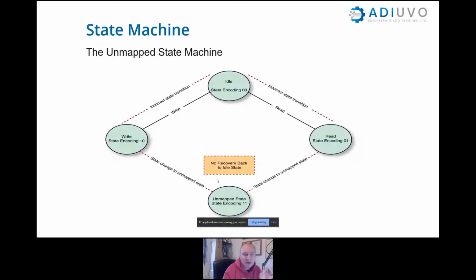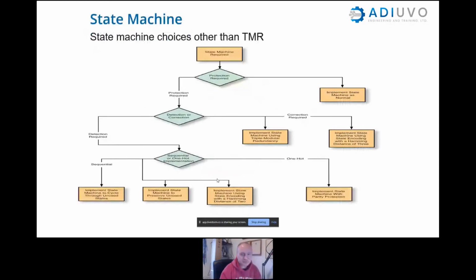And we need to carefully think about how we can design our FPGAs to be able to mitigate that, because the first thing you get taught at university, on a course, is you put a when others in VHDL, you put a when others statement at the bottom of your state machine, in case this occurs. The second thing you learn is that the synthesis tool just strips that out straight away and never actually implements it, because there's no path into those states, so it's not needed.